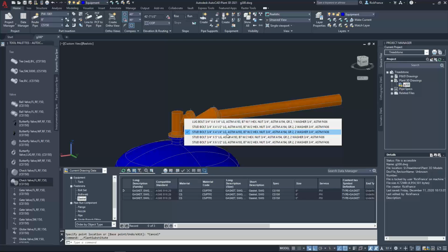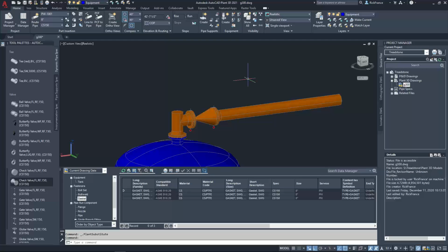So at this point, what you see is I can set this bolt standard and these bolts up, and I can manually change from one bolt's length to another and have those options in my project. But I want to take it a step further. I want to be able to automatically have it assign a bolt length to certain components, or to automatically assign a rounding to certain components. And I can do that through the EndCodes and the connection settings.